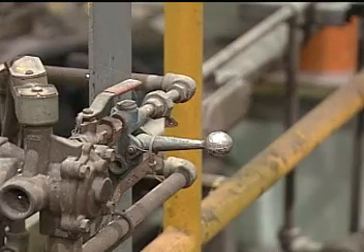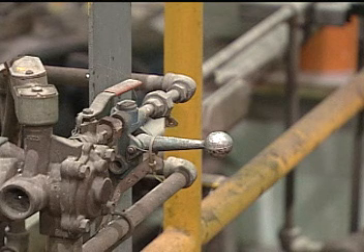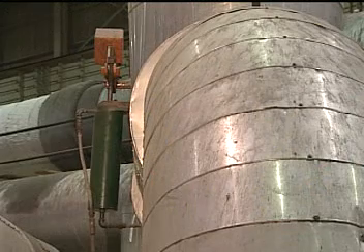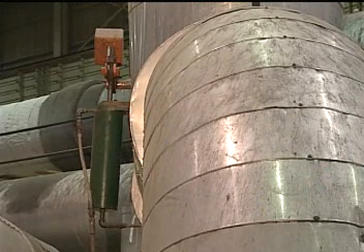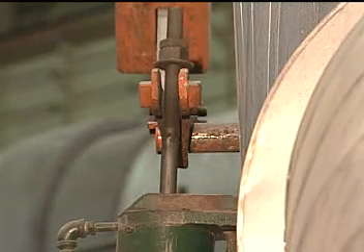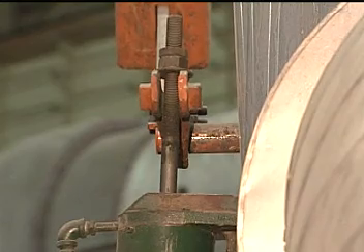Many non-return valves have air assist actuators that are connected to the valve disc. The actuators automatically trip closed if the turbine trips. The non-return valves also protect the turbine from damage caused by the backflow of water if there is a high level in a feed water heater.